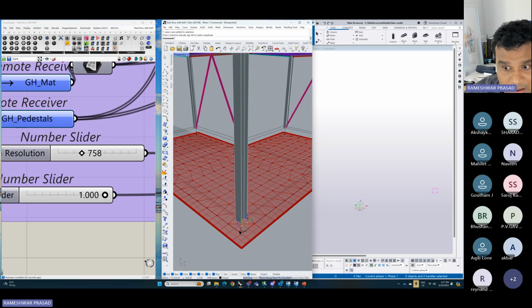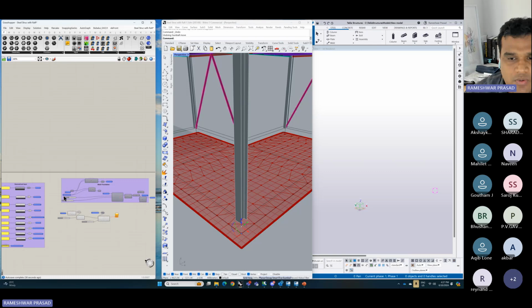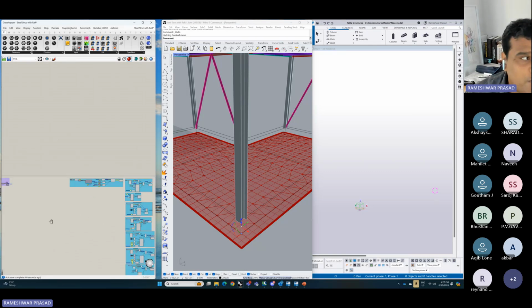I'll have to import it. I will not mess around with it now, but if we change it and rerun it, then the mesh will incorporate that node point as well. A common node will be created at that point, and all the mesh will have contiguous borders at that particular node. Okay, so it really eases up the meshing process using third-party meshing tools.